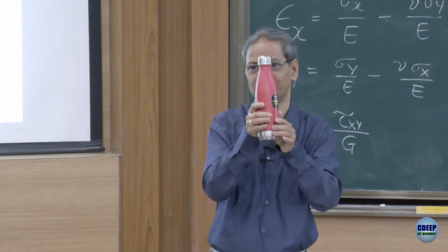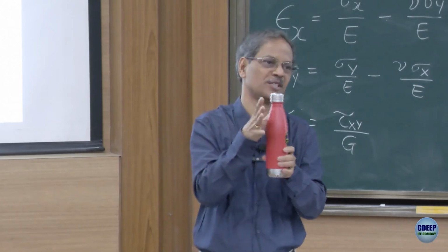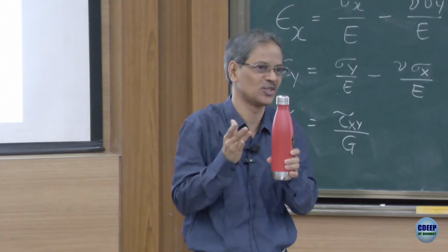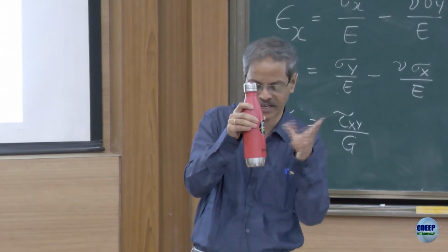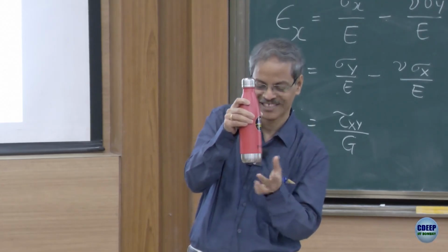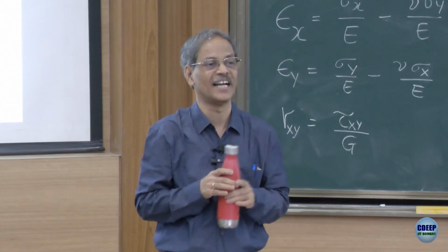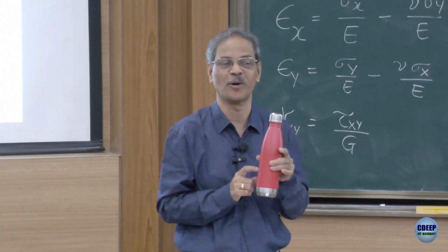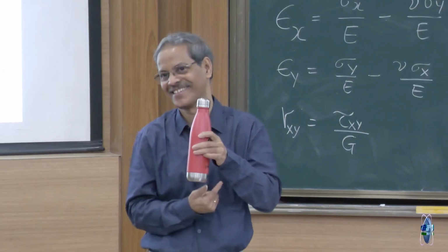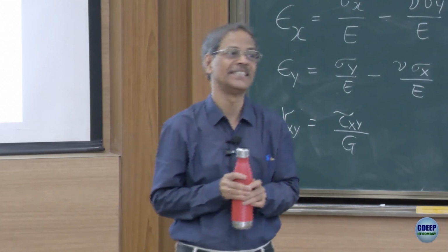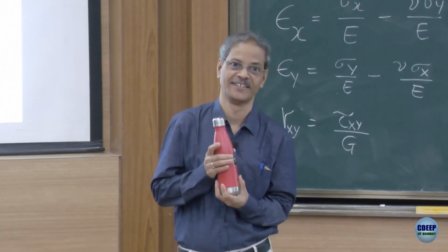If I have this cylindrical geometry, and I have subjected it to a load like internal pressure, which is symmetric, but I have not held it all around at one end, and whatever boundary condition I am applying is at some selected point, then that is not axisymmetric. It will not permit axisymmetric variation of displacement, strain and stress. Is it enough if the boundary condition is axisymmetric? Pardon?